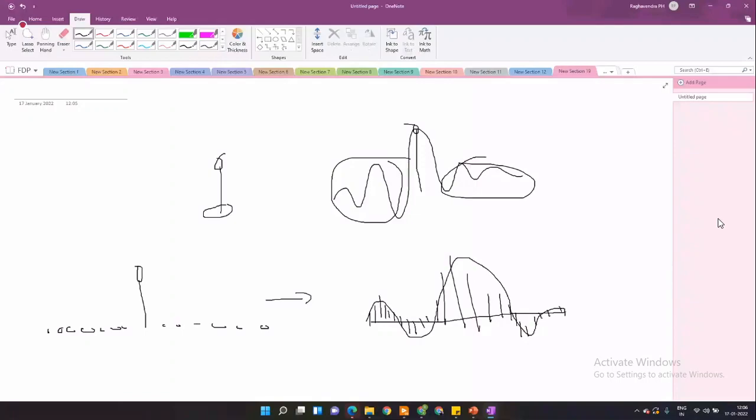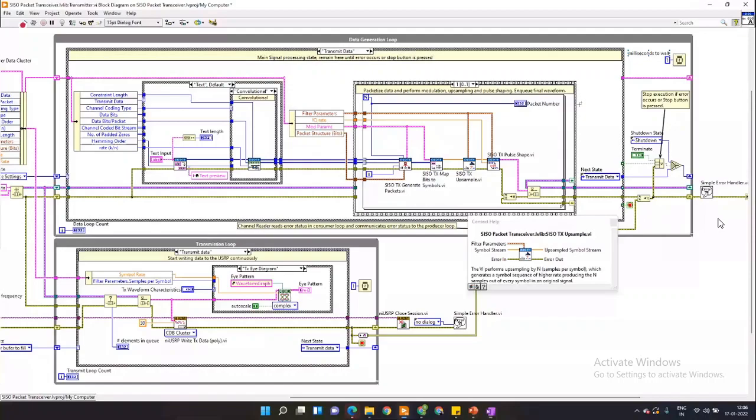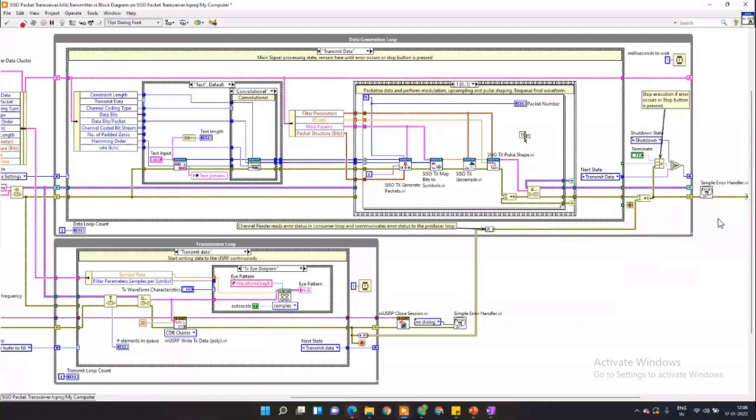Please don't confuse this with the digital up conversion that we do in the USRP. That we do because of the ADC rate. We want to match the ADC rate. Here we do it because we want to get a proper shape for our pulse, which is why we upsample it over here. The usual upsample factor that we keep is 16 because this seems to work very well for us. But you can actually go down to things like 4 and 8 depending on your application and your pulse.